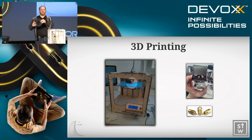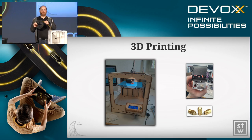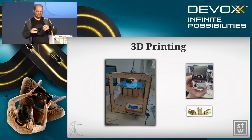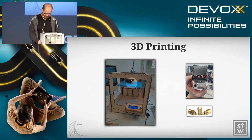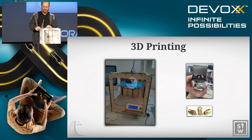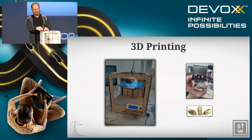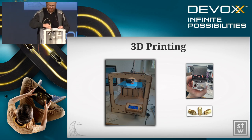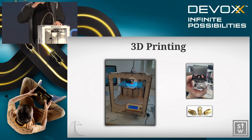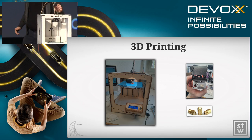It's just PLA wire that you heat up to 210 degrees, or a bit more or less, depending on what you're going to print. And let me put that back. Yeah, and then this goes through this. It's just a plastic part. It goes through here, and then it's heated here, and then it creates the objects layer by layer.